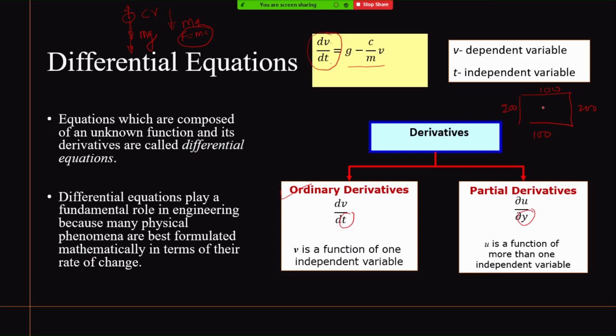So the temperature at this point depends only on the x variable as well as the y variable. So now I can write that temperature depends on x, and temperature depends on y. It is a second derivative because it follows a second derivative, and then I can write an equation. This equation is called a Laplace equation.